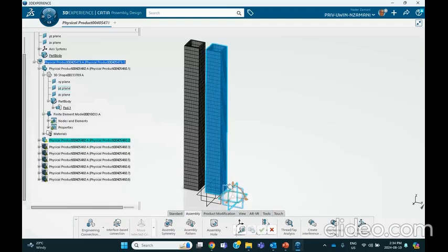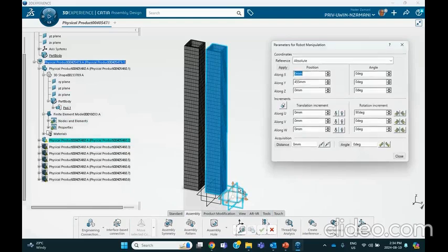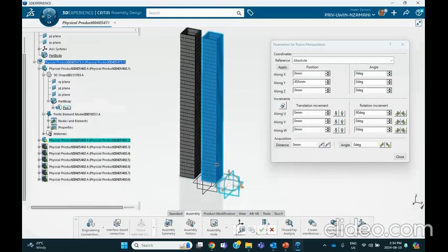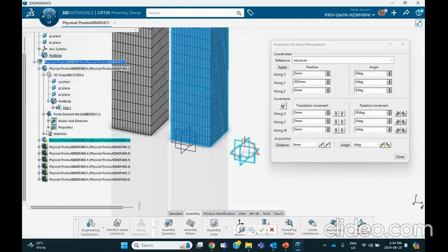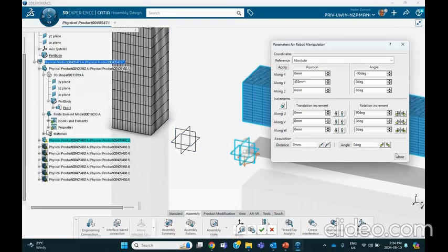Notice that the coordinate system is placed here. I want to rotate this thing by 90 degrees. So if you just double click on that coordinate system, and we're going to rotate this thing about, let me see now, what is this? About this direction. I believe that this is X. Let's check it out. Ah, there we are. Very good. You say, okay.